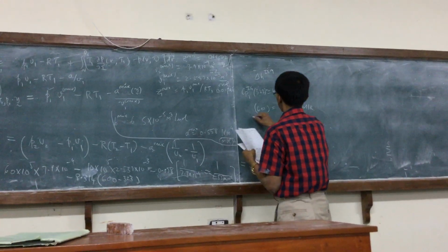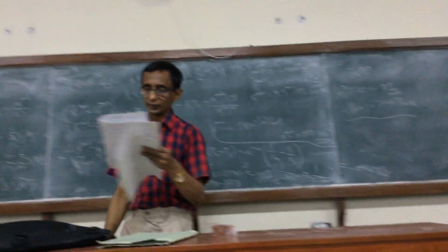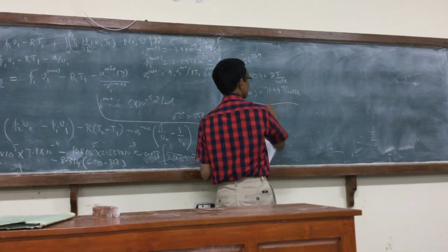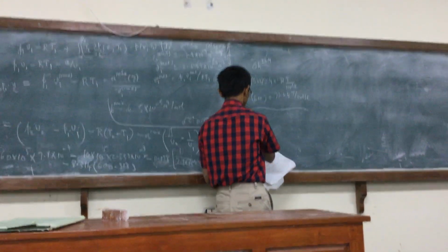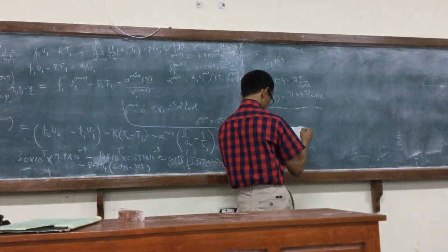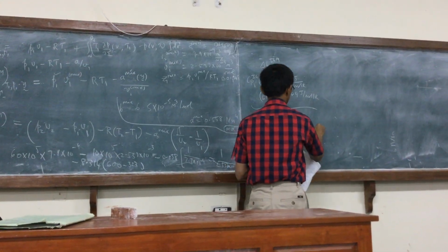So obviously this has a fairly important temperature difference. You cannot just assume it as a constant, but actually use an average. I just took the average of the two and calculated a rough average for component 1 to be 59 joule per mole per Kelvin.